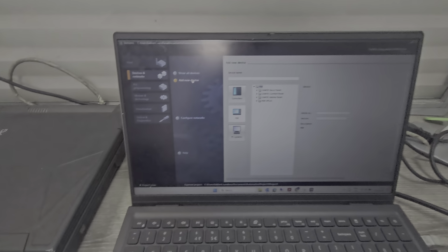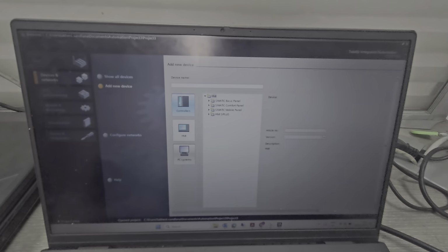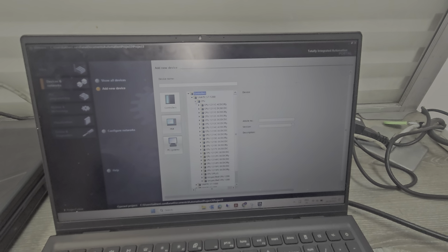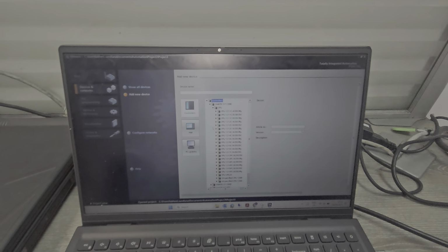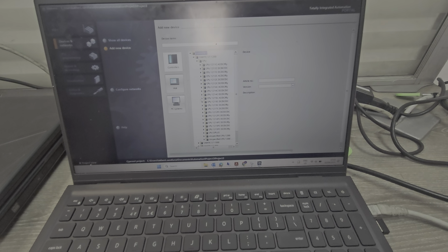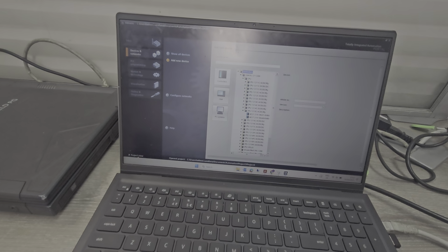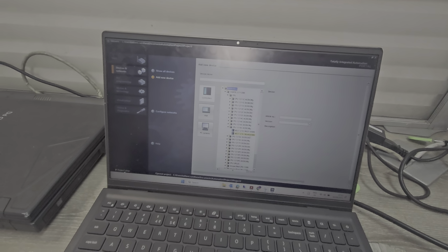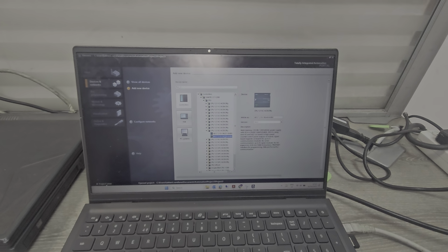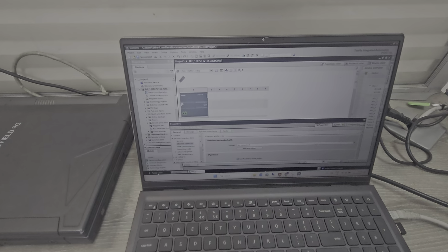It's a bit slow. So now, which device are we going to configure? It's a controller, which is this PLC, and then it's an S7-1200, and I think this one, if you look on the device, it's a 1215C, 1BG40-0XB0. Okay, it's this one. Version 4.4, 4.2, and then let's just wait a bit.